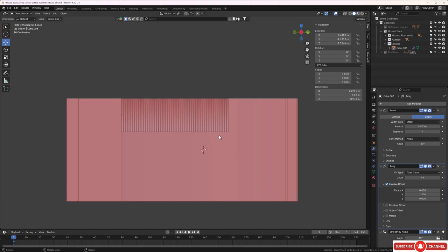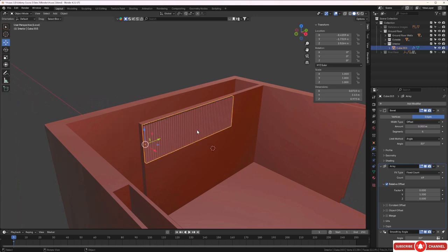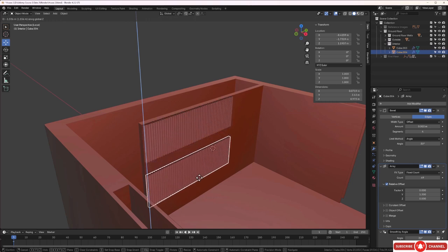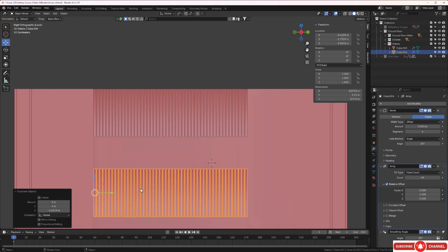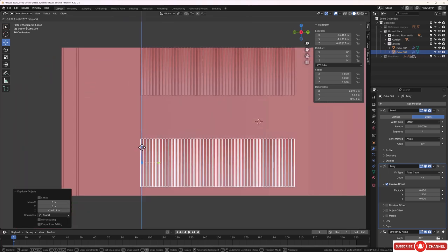Okay, now I've done that, I'm going to leave this bevel modifier active. And I'm going to press Shift-D and Z and bring a copy down. And I'll press 3 again to get it in the orthographic view. And I'll go ahead and carry on bringing those down to, I'd say, about there, like that.